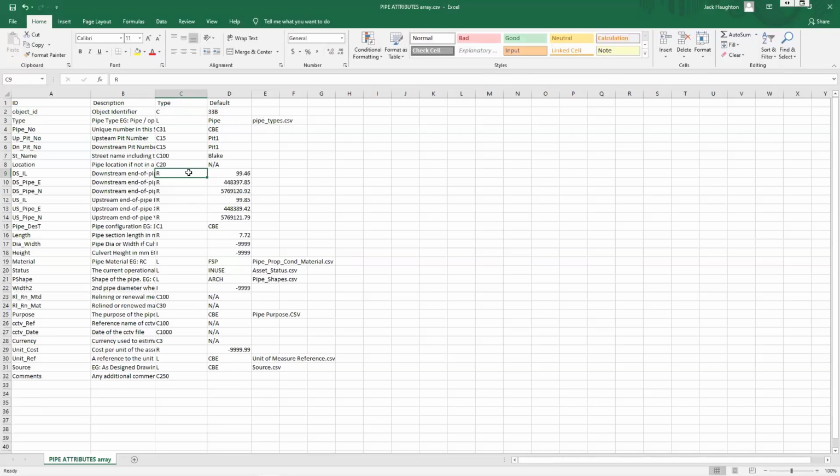If you have an R value, that just means that you're able to input numbers. A C value means that, again, you're able to input what you want. An I value is a negative value, so you're able to use a negative value if you so wish. I believe that's it for in here. So yeah, that's how you go about using that. Anything you put into the default value, that is what's going to initially come through, if that makes sense. So whatever's in here will be what first turns up, and then you can move on and edit it further from there.